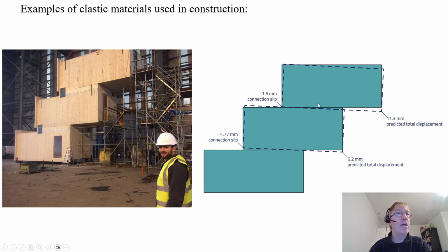And within that, we had to calculate a number of things. We had to calculate the slip in the connection. Not just the instantaneous slip, but also the deformation over a period of time. We had to calculate that and predict that. And it's the same behaviour. We have the load on, load off scenario where there's no time involved, or you've got the time. Now that's been on site for about 8 years, I think. So we have calculated what that would expect to be, and it's all within tolerances, but we do have that.